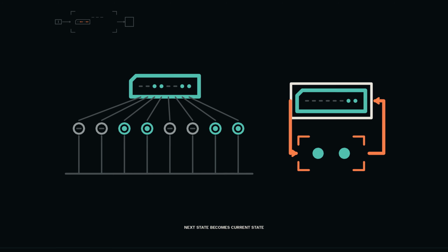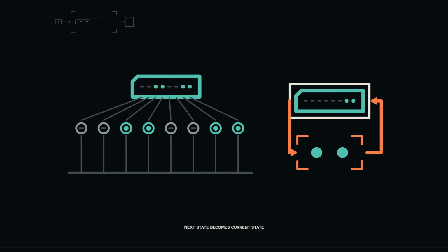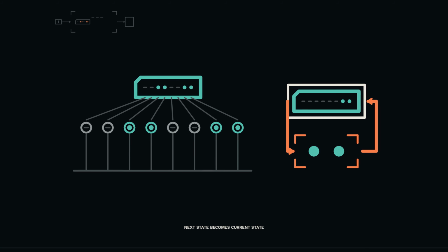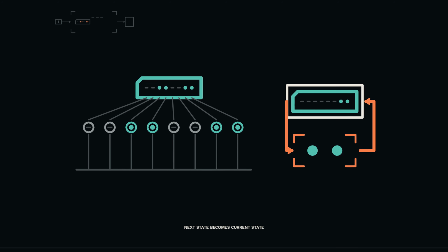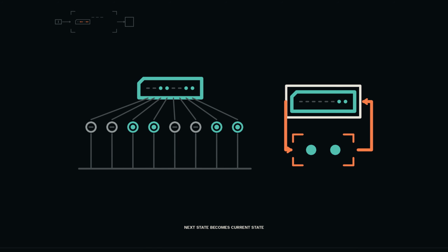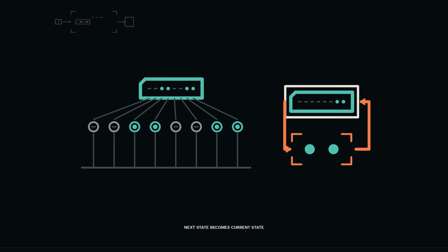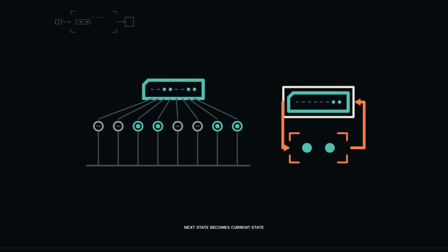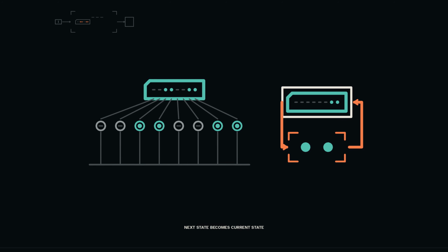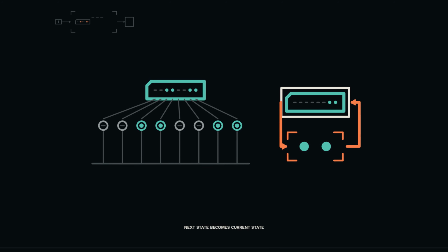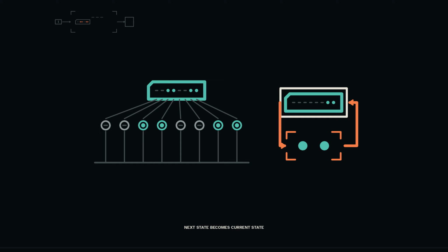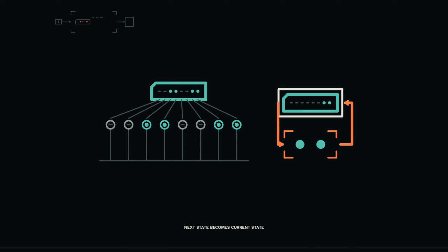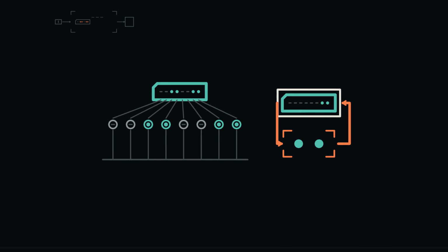What follows the pattern of 8 ones? Every position is a trailing one, so each becomes 0 and no position remains inside the register to receive the final carry. The next stored pattern is 8 zeros. The counter has wrapped after 256 distinct states. This is not an arithmetic error in an 8-bit contract. It is the consequence of fixed width. Whether a later operation treats the discarded carry as important depends on the exact interpretation and flags we will build.